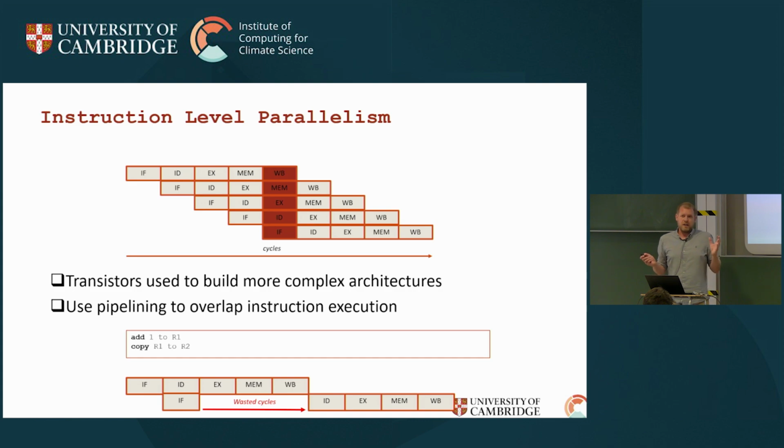The problem with that, and this example, by the way, is an ARM architecture, so it's a really simple pipeline. If you look at a more advanced pipeline, there can be 20-odd stages of overlapping pipeline stages. So they can get really complicated, and that's why they're quite good at hiding bad code, because this complexity in the architectural design can overlap all kinds of things that could occur, and it means that you can get reasonably good performance out of quite bad code.